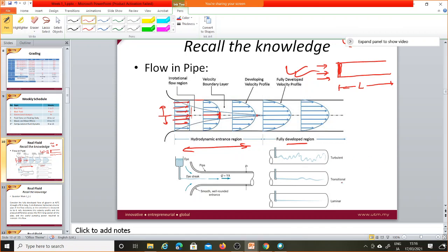flow, turbulent flow. We can do an experiment, which we call the Reynolds experiment, because we separate turbulent, transition and laminar flow by the Reynolds number. Okay, so I think you already know these things, but anyway, I will go through those parts again. So basically what we do here, we have this pipe. It could be horizontally placed or vertically placed, that should be okay, but we have the dye here, and we consider the dye, and we try to trace the dye.